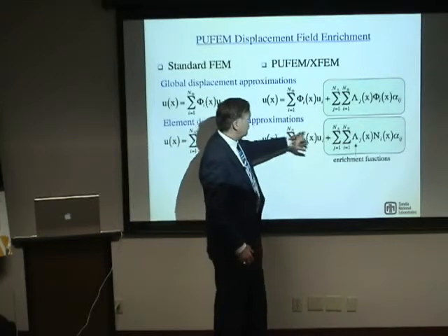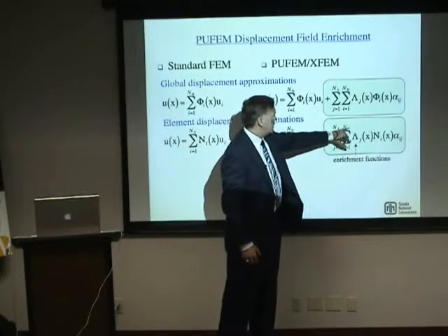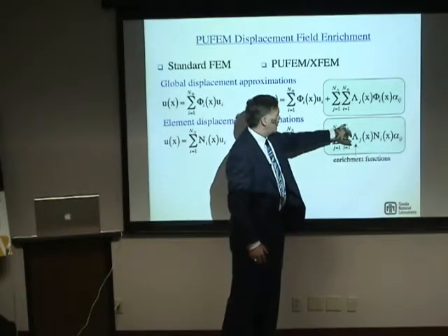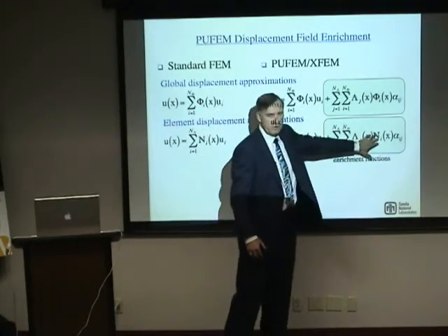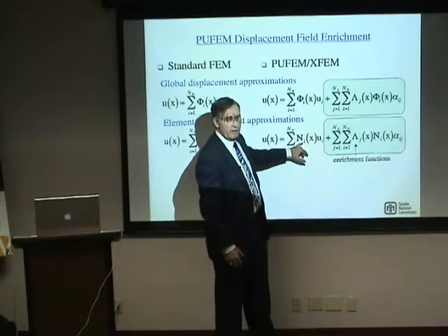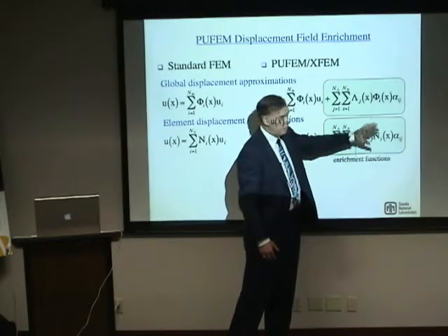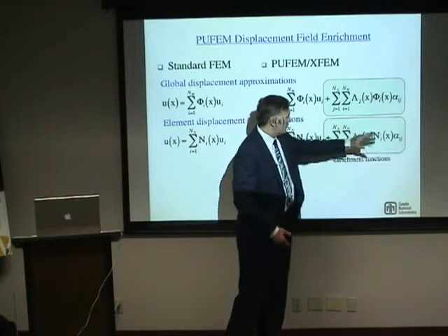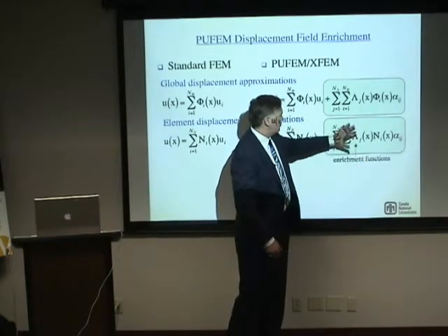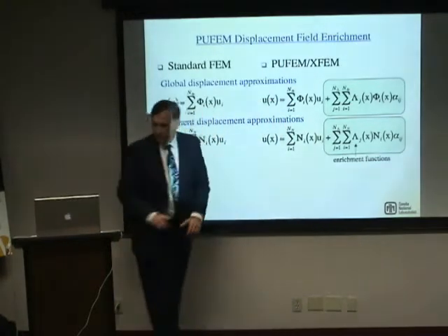The notation is a little weak here. We could constrain this so that it was okay, but in some cases this is not. We could call this n sub n bar and have this represent a different set of shape functions here, still a partition of unity, but for example you might use quadratic shape functions for this and you might use bilinear over here. Now, in general, you could still use this equation by constraining your alphas, but it'd probably be more explicit to indicate that they can be different. So as such, we bring it in this product form.